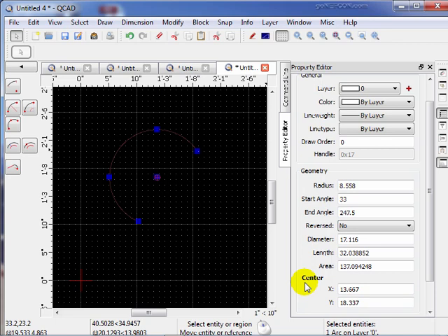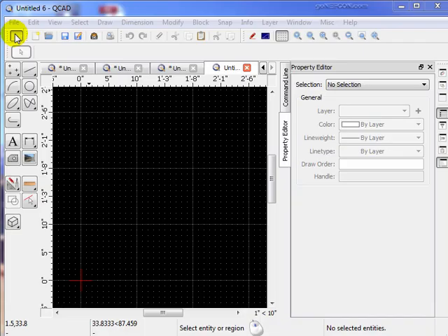And that's how you place an arc using the command line. Next we want to draw another arc, the same type of arc with a radius and a starting angle and ending angle. Let's say we don't know the angles, but we have XY coordinates on the drawing area where we want the angle to start and stop. So in that particular case, we can't use the command line because we don't know the angles. Can't use the arc with the command line.